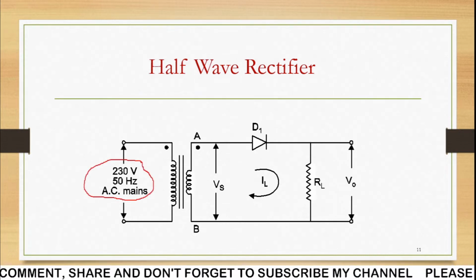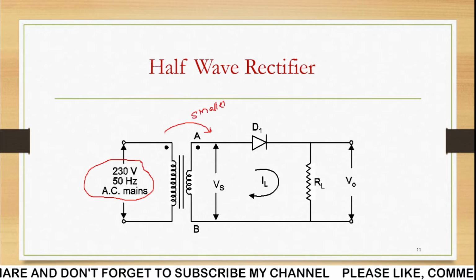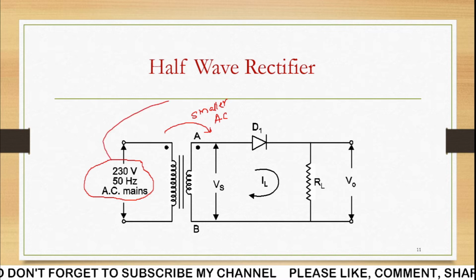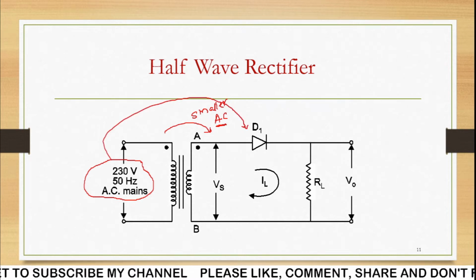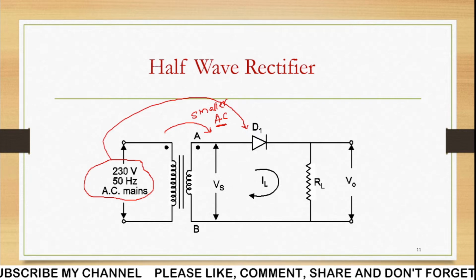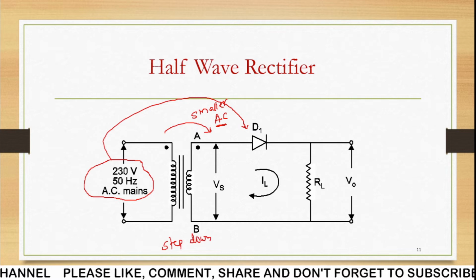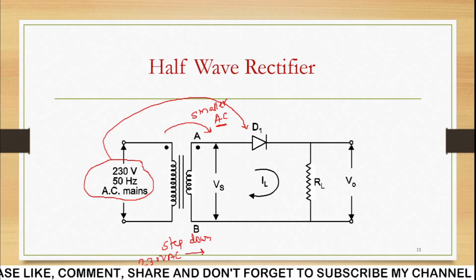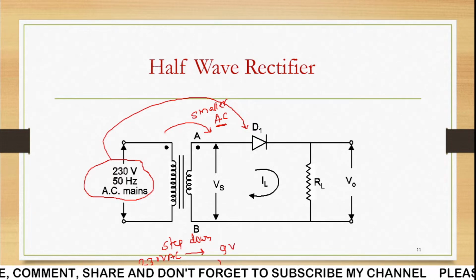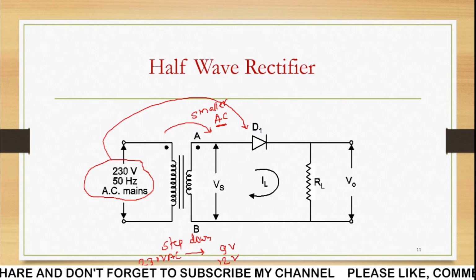So it should be converted into a smaller AC, because we cannot provide such a large AC to this particular diode. We are going to provide a smaller AC voltage, so this transformer is a step down transformer. It will convert the 230 volt AC into a smaller AC like 9 volt AC or 12 volt AC and so on. This smaller AC is fed to this diode.